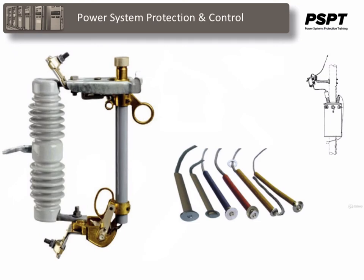This is a typical distribution type fuse system. Generally speaking, they're all pretty much the same, and the construction is very similar to all of them. This one in particular has a fuse mounting. As you can see here, it's bolted to the pole to connect from the line to the device that's being fused, such as a distribution transformer here. The fuse holder itself is located here, and fuse links go inside the fuse holder. Line terminations are made on each end of the insulator.